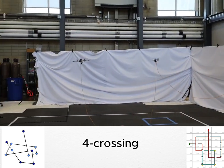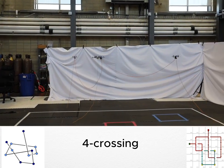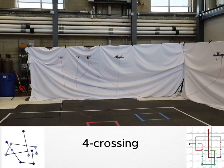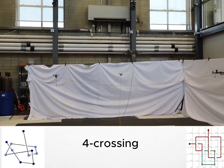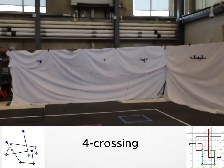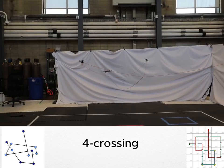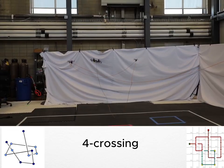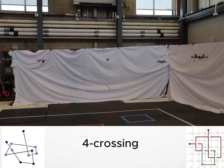The cable is held by one lifting robot at each end, and supported at key points by intermediate robots, as determined by the loop consistency filter. With fewer robots than the baseline grid method, the cable naturally relaxes into smooth spans through the action of straightening and spring damper forces. This allows the team to preserve the knot's topology while reducing redundancy, demonstrating efficient midair knot formation.